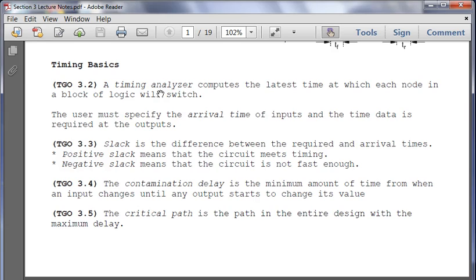You get the outputs, and then you use the initial carry from the first half to serve as a multiplexer for those two outputs. So it cuts the runtime in half, but you gain 3 over 2n space complexity plus the multiplexer. So that's where you, as an engineer, trade off. Do you want it really fast or do you want it to be cheap? So critical path is a big consideration in that.